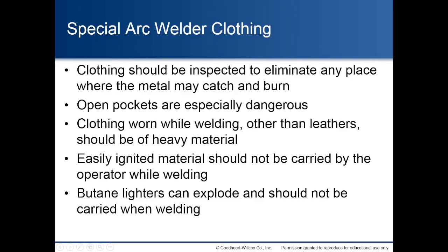Special arc welder clothing. Clothing should be inspected to eliminate any place where the metal can catch and burn. Open pockets are especially dangerous. Clothing worn while welding, other than leathers, should be of heavy material. Easily ignited material should not be carried by the operator while welding. Butane lighters can explode and should not be carried when welding.